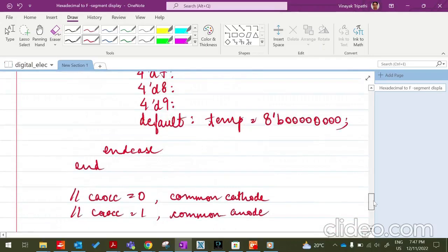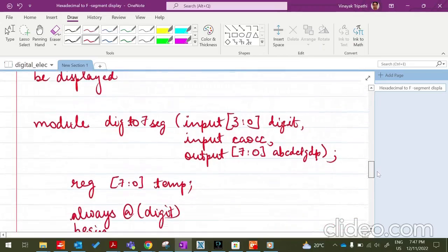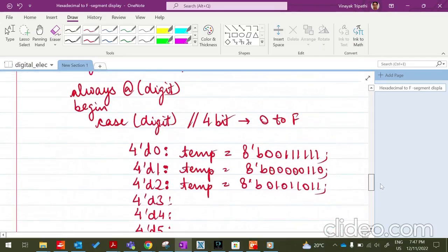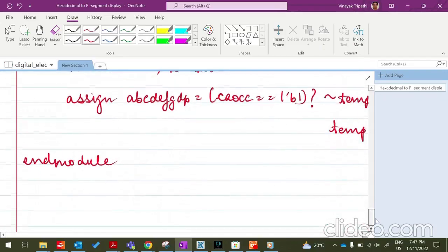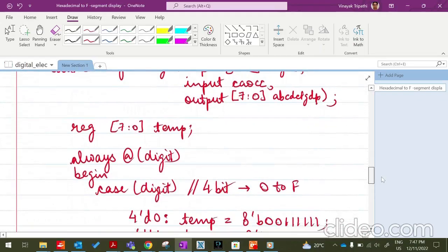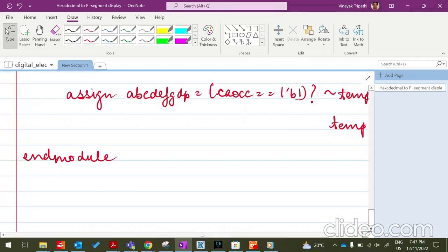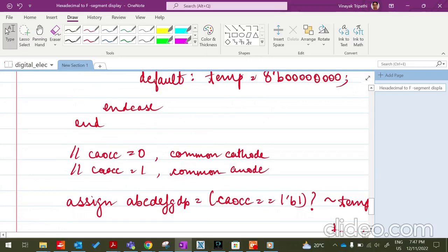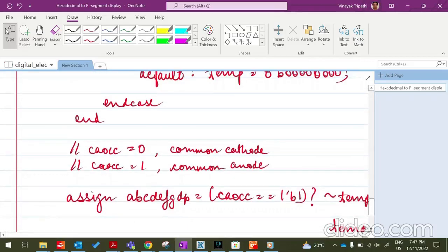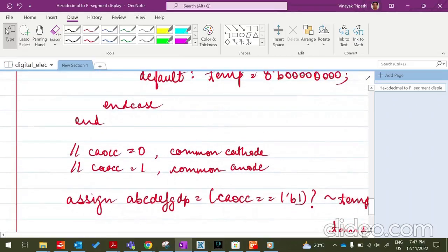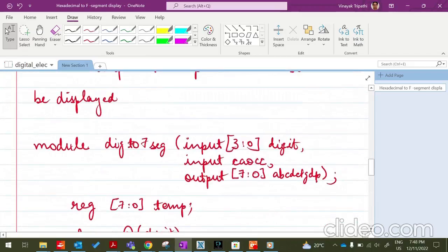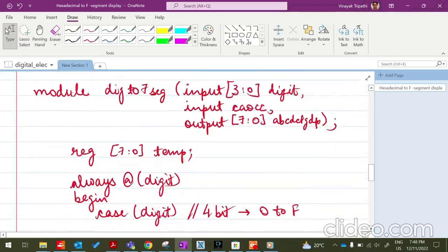So this is a very simple code which I have written, which I have shown you. I have just shown you the concept. I will be showing you how the full code will be written in Verilog, or I have almost written it, but how it gets compiled and how we'll write a test bench for it to see how the values get displayed on the waveform. And we'll try to synthesize it also on EDA Playground through Mentor. I think Mentor Precision is there on EDA Playground, through which we can synthesize this, and we will be seeing what circuit actually it's making, right?